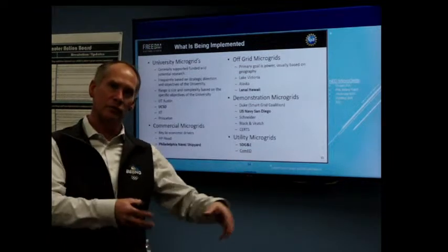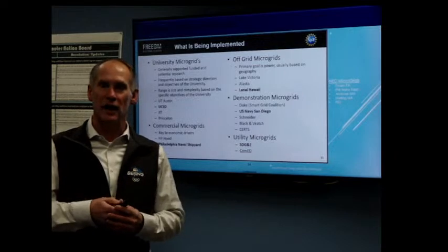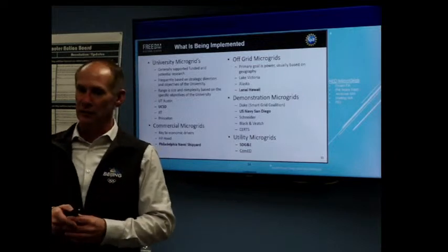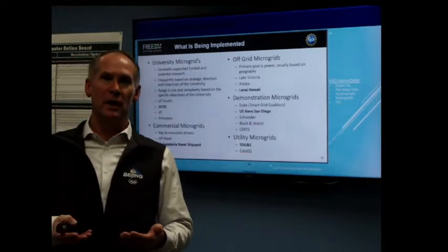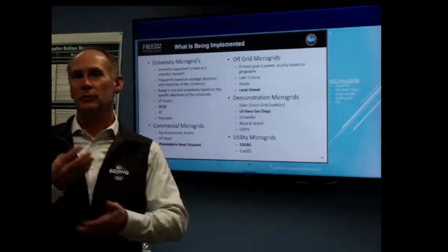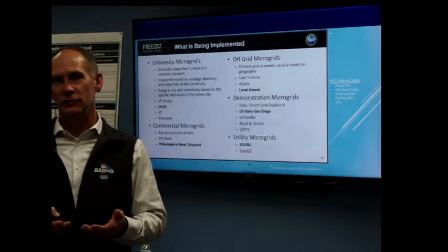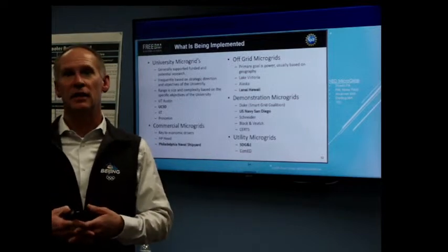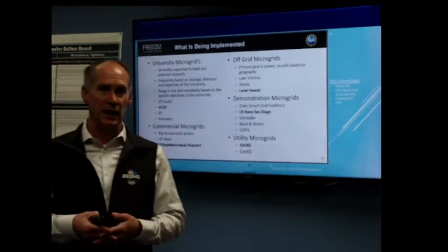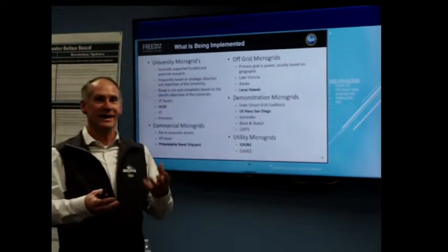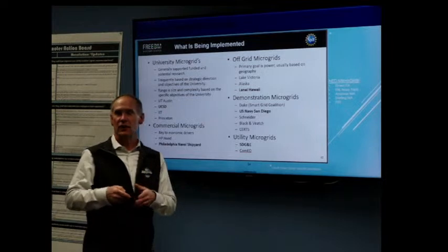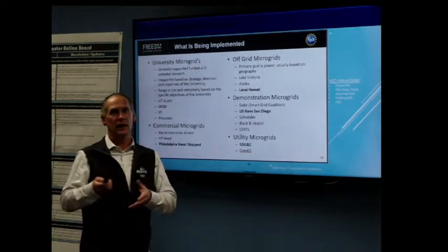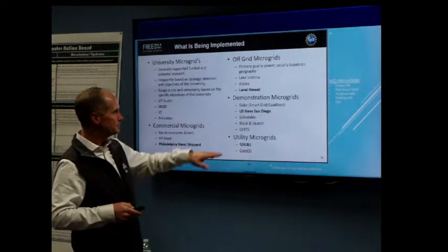So what they did was they drilled down, they had their own natural gas, they have a tie-in pipe from the natural gas systems, but they're generating and operating their own microturbines. Those microturbines are actually providing a 12,000 volt utility grid that they own for the entire Masonic Home campus. That's a microgrid, and they've been using it for 15 years. They've also been tying in solar power and other uniqueness to their microgrid.